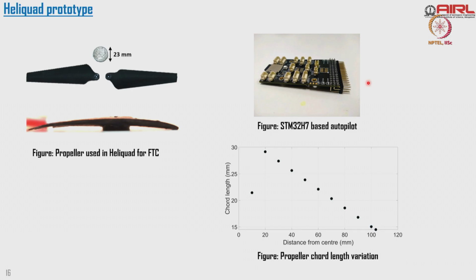In the course we talked about what sensors we are using, how we can model the sensors, and the complete mathematical model of the dynamics of the quad, which we can write in Simulink. Once you have it, design the controller, and once you do the controller you can directly download it from MATLAB to any STM32-based flight controller, right. A Pixhawk you can do it, Cube Pilot also you can use, you can download directly onto the Cube Pilot.